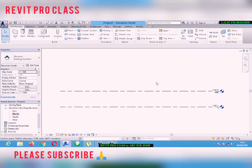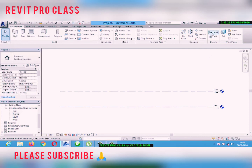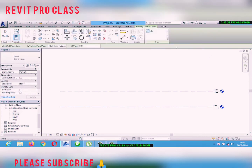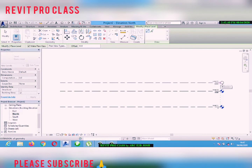So we want to add more levels according to how our model will look. The first thing you're going to do is pick Level from the top right-hand side of your interface. You click on it, then you drop it, and you freely drag your mouse, then you drop it again.